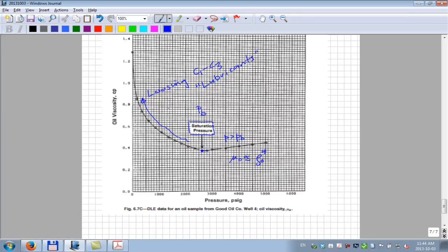But for practical purposes, you can also say that the viscosity here is proportional to the oil density to some power. But you don't have the same components behaving differently, and the density is changing for another reason. I like to think of this viscosity increase below the bubble point as a result of the loss of these light components lubricating the oil, making it less viscous.